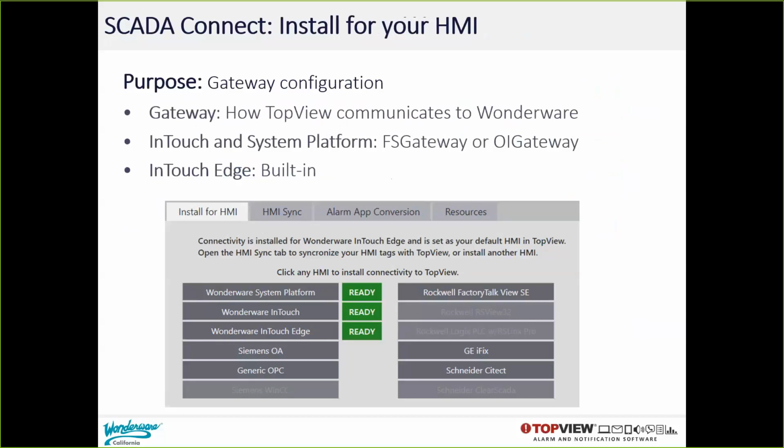Let's take a look at SCADA Connect and how it works. The first step is called Install for your HMI. This lets SCADA Connect configure your gateway, which is the communication layer between TopView and Wonderware. For System Platform or InTouch, TopView uses either FS Gateway or OI Gateway. And for InTouch Edge, the gateway is built in.